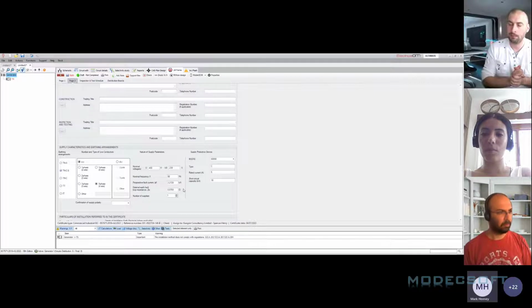So I think you've already answered my question: should that circuit continue and you've got some end user loads, final circuit loads, etc., you would really need to run your report. Not the report, you'd need to switch between supplies to actually see that you're going to disconnect within recognized times, aren't you?